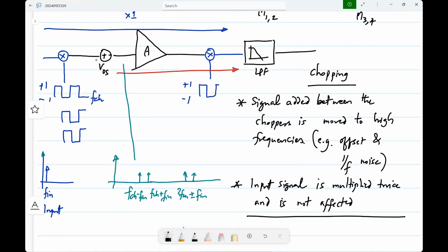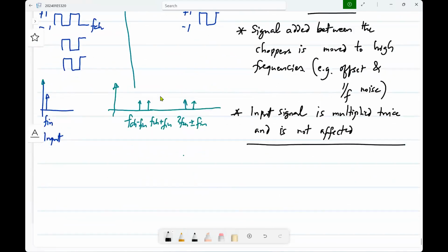So these dynamic techniques are interesting. By nature they can be used at low frequencies. But of course, what is low frequency has been going up as a result of technology advancements as well. Because what is high frequency for a 180 nanometer circuit can be a medium or low frequency for a 18 nanometer, 16 nanometer circuit. Okay. So you can use these things at higher and higher frequencies, right? So just quickly, another example of dynamic techniques is